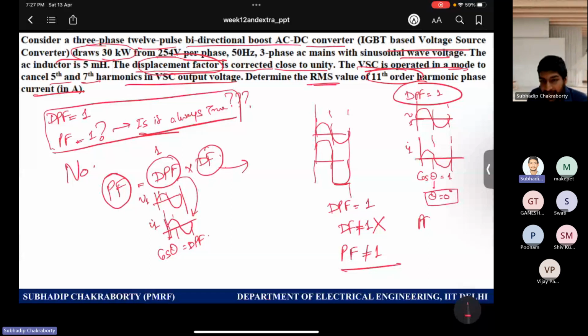If it is lower than 1, then there are more harmonic components and only a small amount of fundamental is present. Since most of the amplitude is dominated by higher order harmonics, the distortion factor is much below 1. In such cases, your power factor will not be unity.